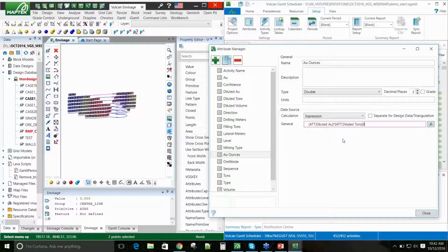And one example of using that confidence variable is via lookup table. So we have lookup tables that allow me to identify the table name. The key is the confidence attribute that I brought in. And then the values, the first column in the table, we can have one key and then multiple value columns, and then a default value if the key is not in the table itself. So this, I have a factor of 1 or 0.9 depending on the confidence level.